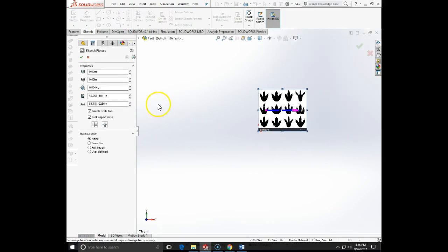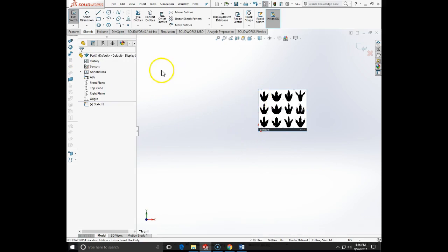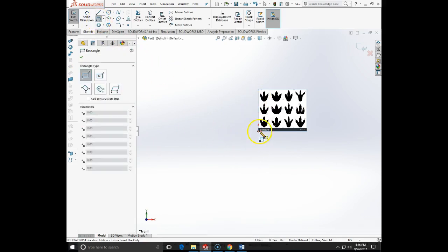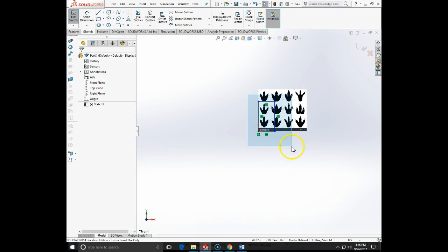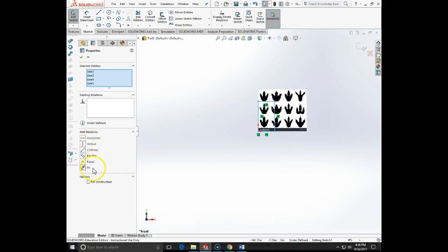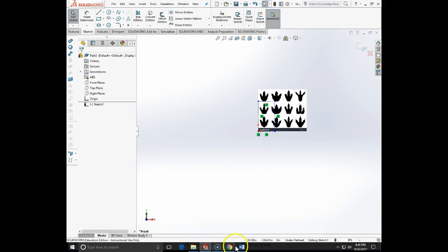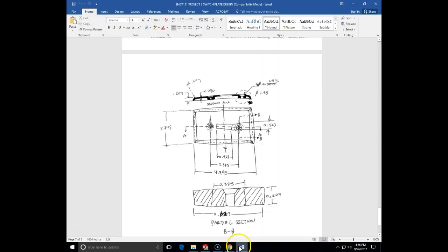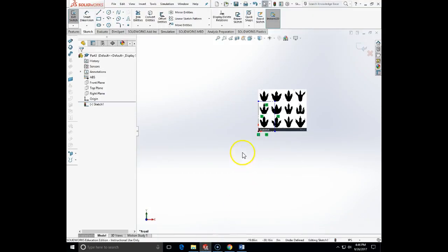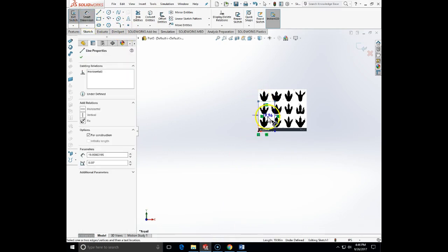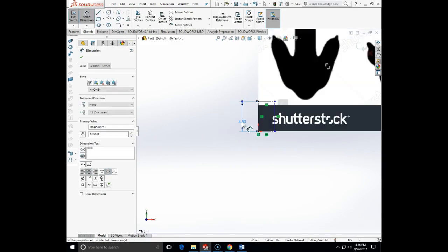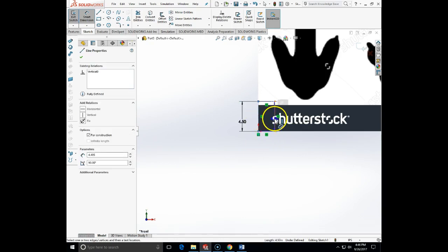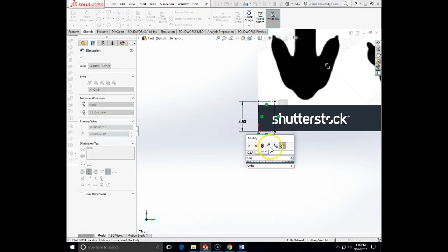However, they are not scaled. For now, I will leave it in there. I'm going now to make my outer boundary of the switch plate, and I will make this a construction line rectangle, and that rectangle is going to be 4.495 by 2.75.